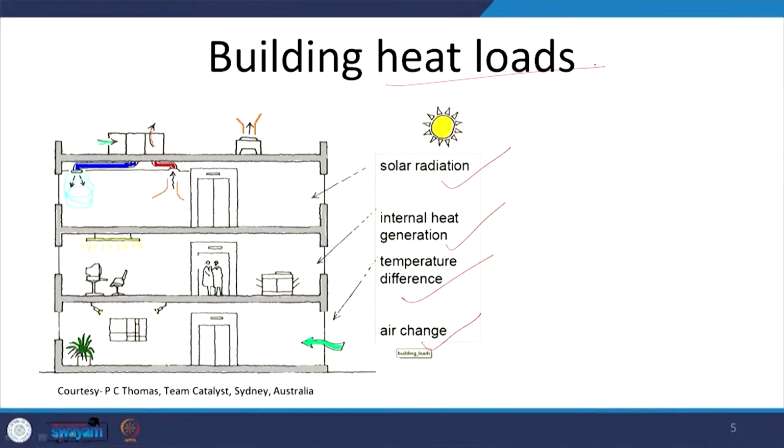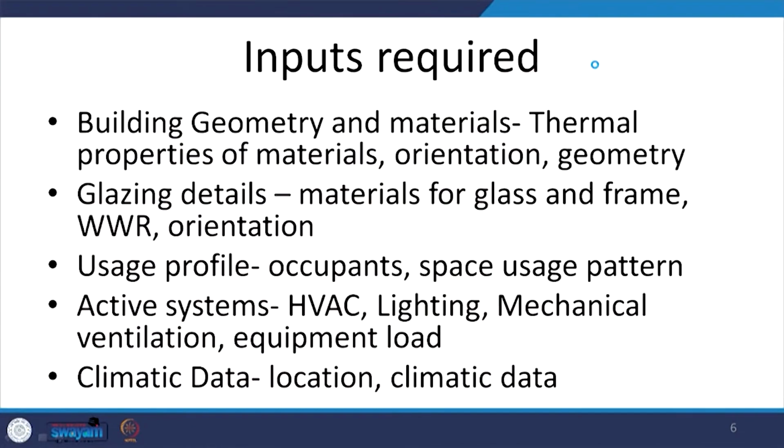So, due to this minimum number of air changes which are required, how much of the heat will be added to the building or how much of the heat will be lost from the building is what will contribute towards the building heat load. In addition to our understanding of comfort and the heat load or loss, we have to add a lot of inputs into the building simulation model. That is when the model will be complete.